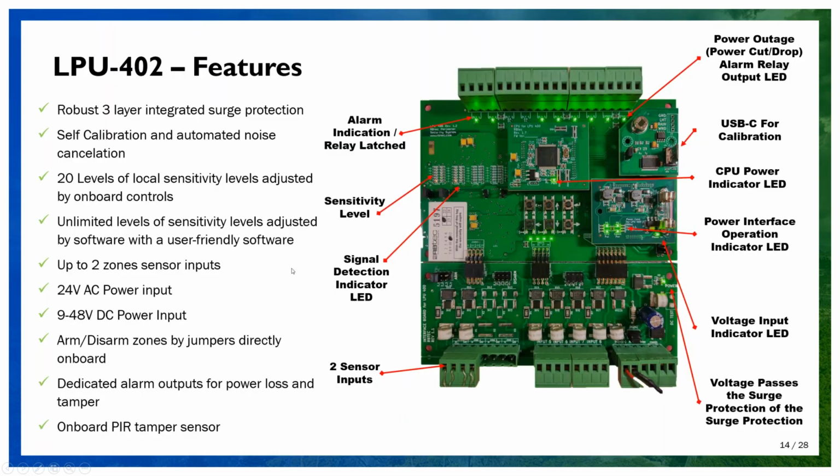So when looking at our processor, it's important to understand a couple of things. First of all, you can see that it's constructed out of two main boards. The bottom board, which is the input or interface board, is mainly surge protection. So in case the board gets hit by lightning, we will replace only the bottom board and not the whole system, which is cheaper, easier to repair, and therefore quicker to fix.